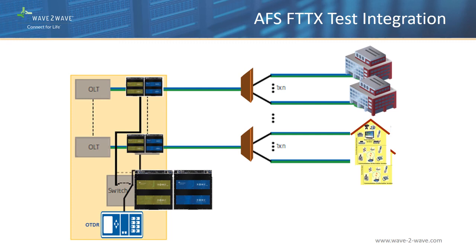A technician arriving at the manhole or street cabinet where the fibers are to be terminated then instructs the NOC to connect the visible light source to a given target fiber, enabling the field tech to immediately identify the fiber. Cycling through this process allows the technician to complete the task quickly and accurately.